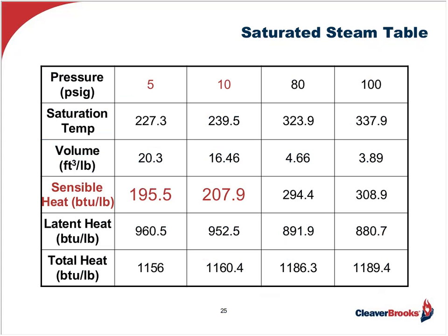To begin with, understand these deaerators operate under pressure with designs most commonly rated at 50 pounds. That's the design pressure of the tank, and operating between 5 pounds and 10 pounds. 5 pounds is 227 degrees, 10 pounds is 240 degrees saturated. Now, there are designs available for higher design and operating pressures, but for our discussion today, we'll limit our focus on 50-pound designs and operating between 5 and 10 pounds.